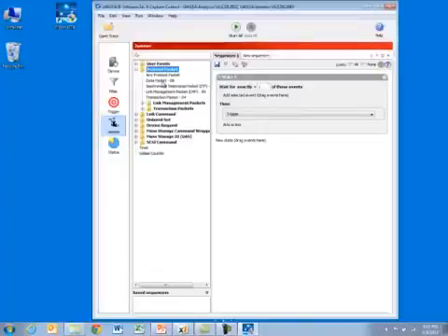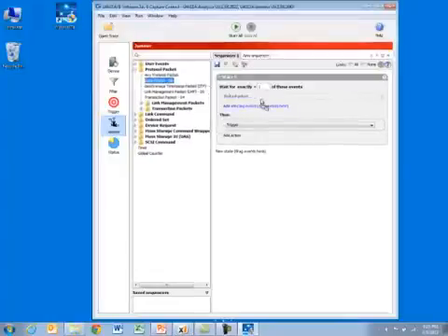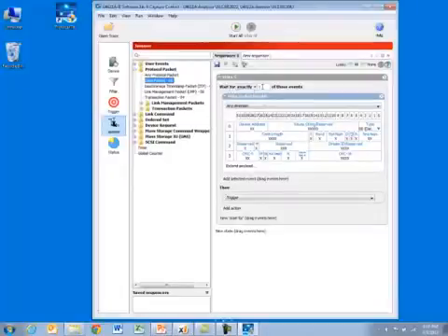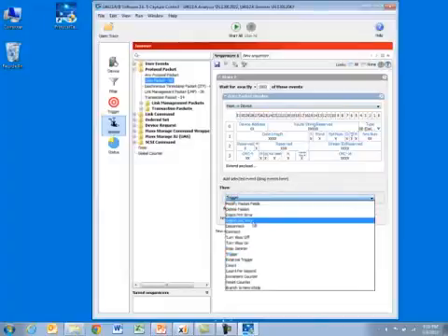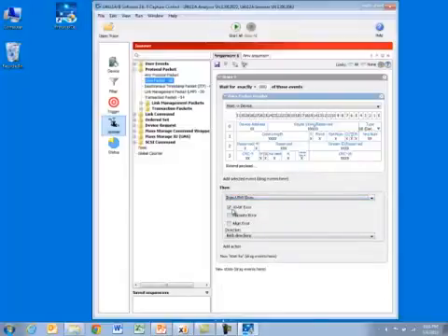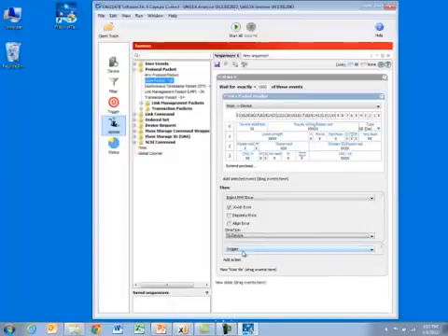For our first simple case, I'm going to say a data packet, drag it over to my state diagram where I'm going to wait for exactly some number of these events to occur. I can say I want to look for host data packets, 1,000 of those data packets, and when I do that, I'm going to inject a physical layer error, a PHY error, a 10-bit error, and we'll inject it to the device. Then we will go ahead and trigger so we know that it occurred.